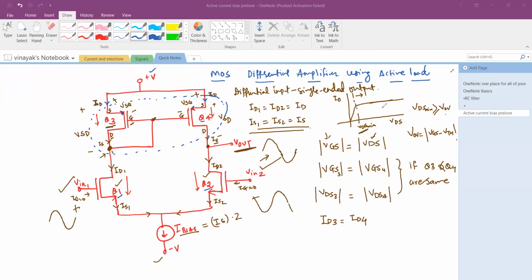Okay, is there anything left? We can also write the expression of the drain current in the saturation, and we also can write the expression of the drain current in the triode region. So I leave it as an exercise for you. And then for the given values of the voltage supplies and the bias current, let's say bias current is 1 milliampere and the voltages are plus minus 3 volts, accordingly, you can get the calculation for the Vout.